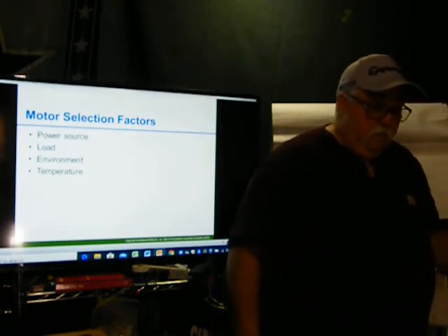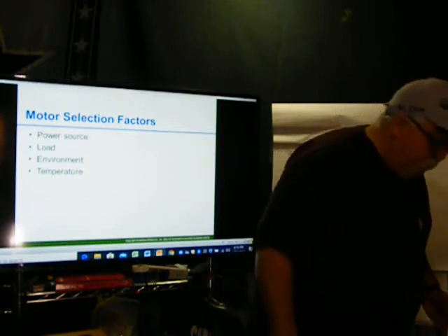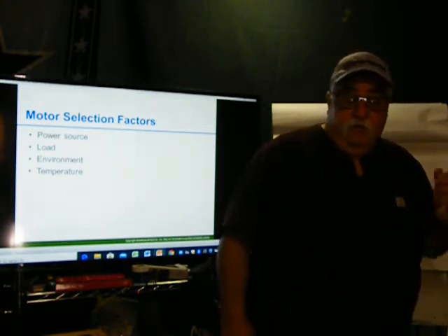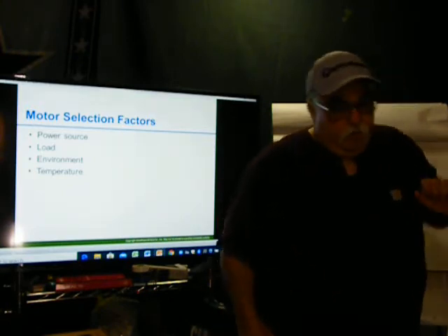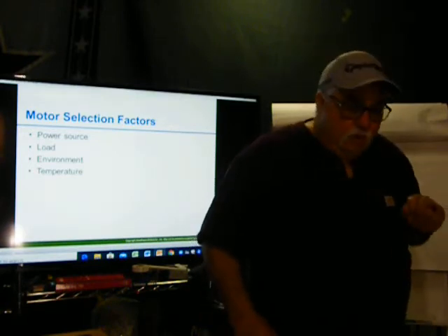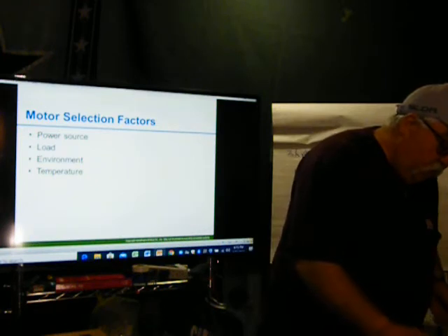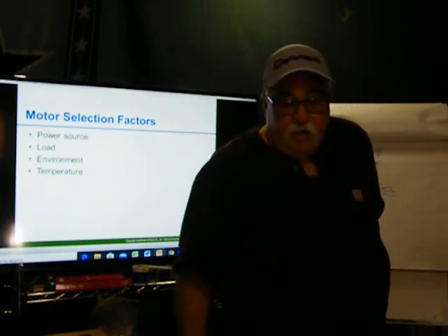You can see 400 to 500%, low and high. So it's 400% to 500% at the initial start, because of the force it has to overcome. And this is where we're going to the locked rotor indicating codes.